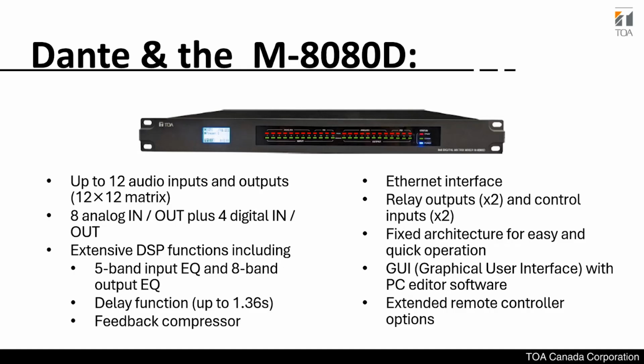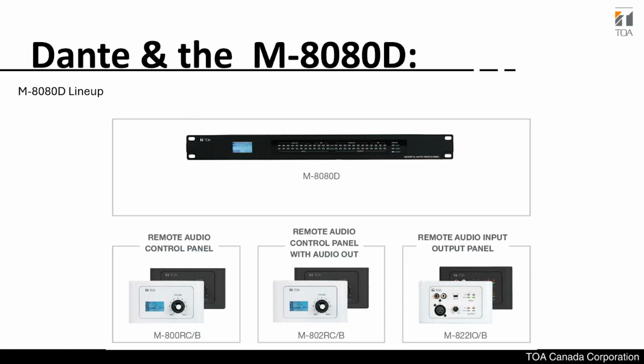And yes, there are extended remote controls. The M8080D has some additional devices which we can connect through the RD port, which we discussed before. This is a digital way for the audio to communicate, but not Dante, which connects directly to the M8080. First is the M800 RC. This is the remote audio control panel. We can select any input to any output. Also, we can load a scene from there.